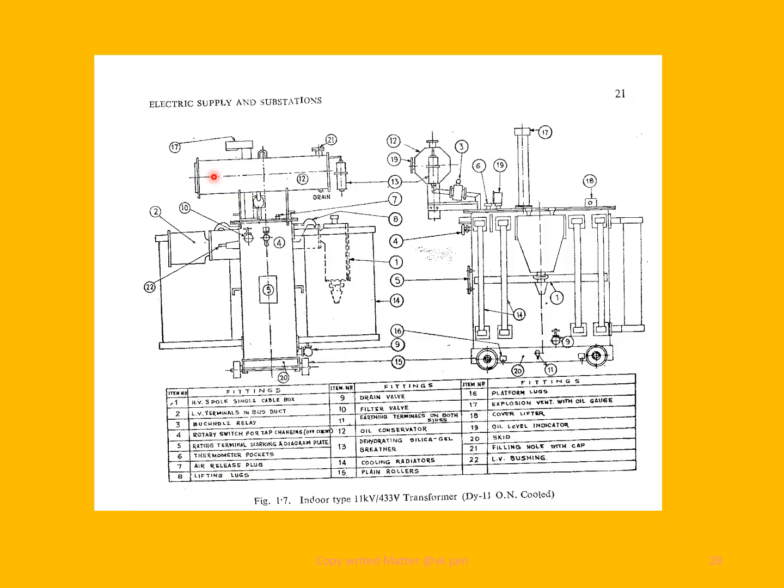This is the oil conservator, and the oil conservator is provided with a silica gel breather. This breather has silica gel provided with a color coding.